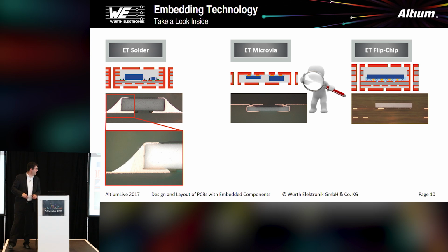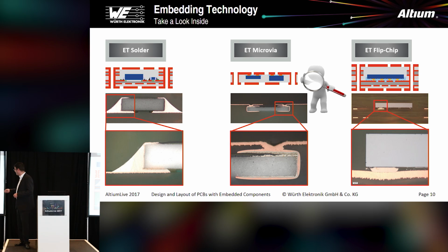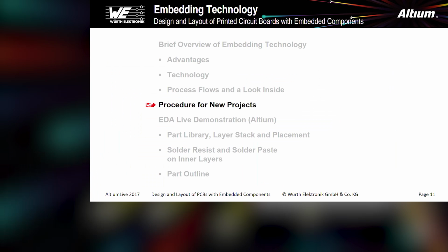For the flip chip technology, it's a little bit different. Here we're relying on active components, which are already being bumped with gold bumps, so that we have a connection here in that case with the gold bumps directly connected to the pad. If you want to have more details, we can talk about that later. That's just a lot of stuff going on there, and it's just a lot of time. But to see the differences, you have those microsections of those kind of things.